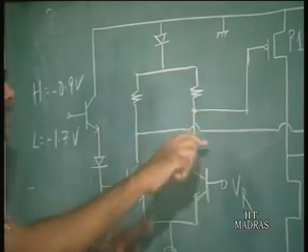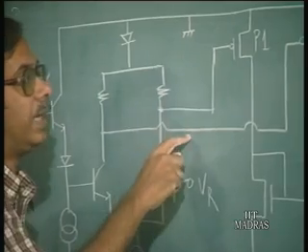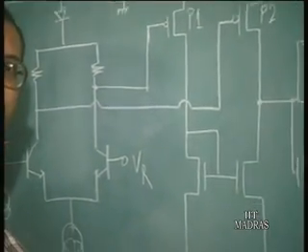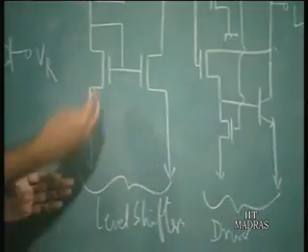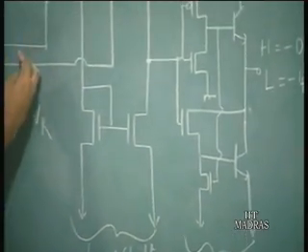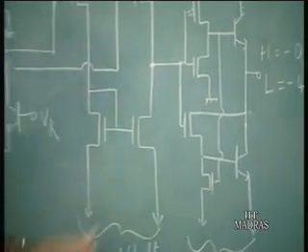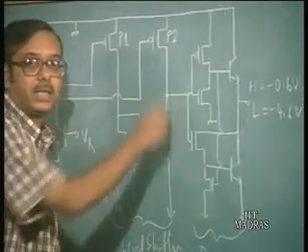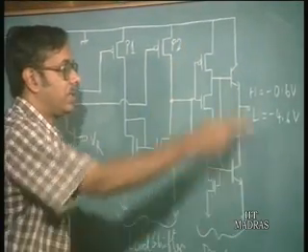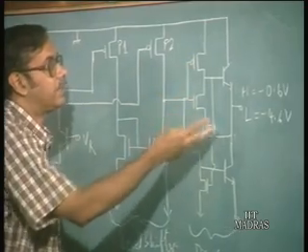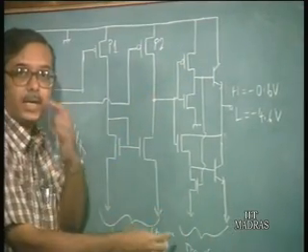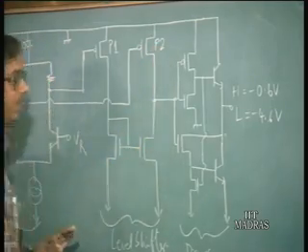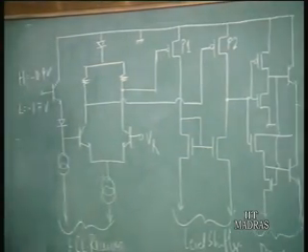So, the voltage levels on these two lines are going to be different, and then what you have is the next stage, which is called the level shifting stage, which basically converts these ECL levels to the levels which are understood by this circuit, which is nothing but a BiCMOS inverter. This is the standard BiCMOS inverter circuit that we have already seen. So, this is doing a level shifting. Now, let us see how this is done.